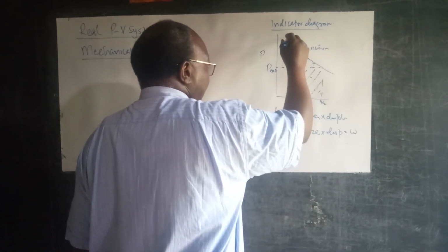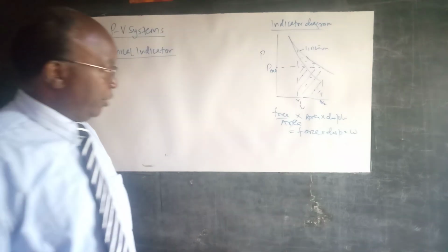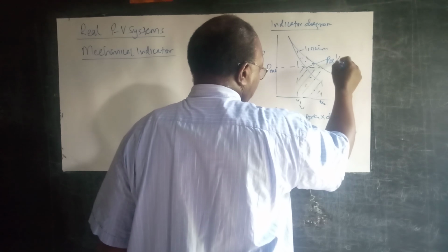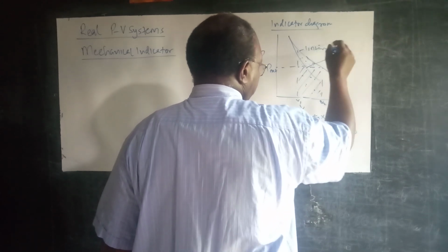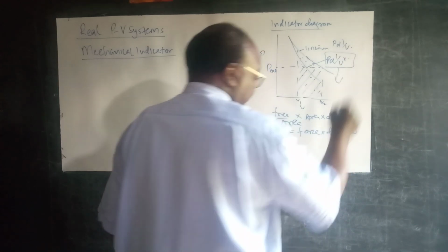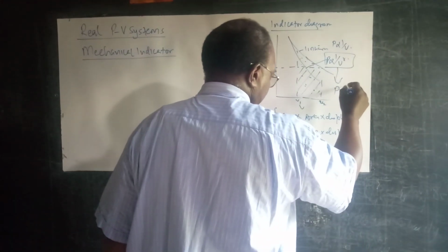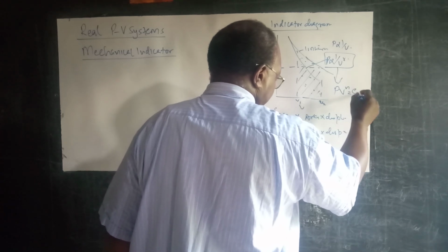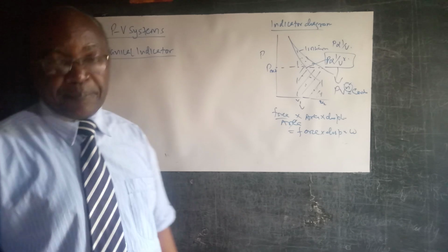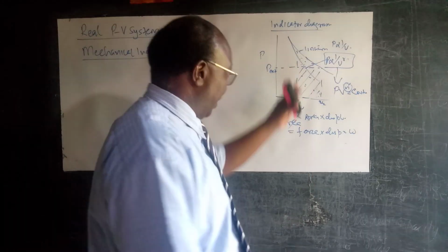But when we have an adiabatic process, which falls under polytropic processes, then you will have this case where P is inversely proportional to V^gamma. Here P is inversely proportional to 1 over V. Remember, for polytropic processes, we say that PV^n was a constant. That's the polytropic index, or expansion compression index. So we just reminded ourselves.